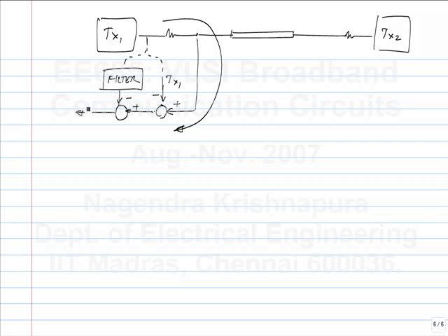Yeah, that's true. I'm just showing it as this thing. Many times it is implemented like this because you get some analog cancellation, and then after that the part that you have to cancel is small. You don't have to cancel a large signal. So in this case, when I draw it like this, TX1 is like the echo canceller that was in the midterm. So it is this memoryless echo cancellation. It cancels a large part of the signal, but leaves a small part behind that is done by the filter. So essentially the signal provided by the filter is small. So that's a practical way of splitting it. But from a purely signal processing standpoint, you can just say that you will find what the echo transfer function is and subtract it off. That's all.